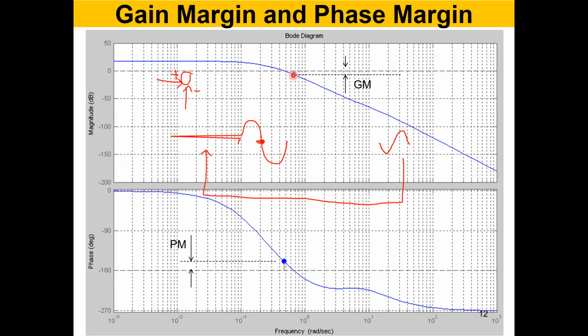So if you are a practicing engineer, right, you need to know what your gain margin is in the plant you are working on, right? And make sure you leave at least, let's say, in terms of absolute gain, maybe at least about 10 or at least 5 as an additional factor, so that every loop you have probably about 0.2 gain, so that it will quickly die out without causing any problems, right?